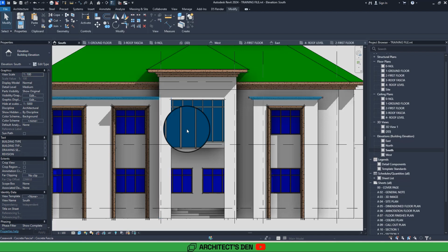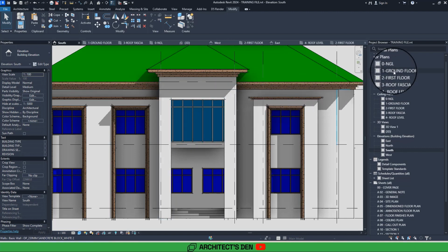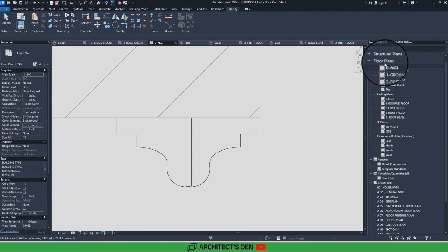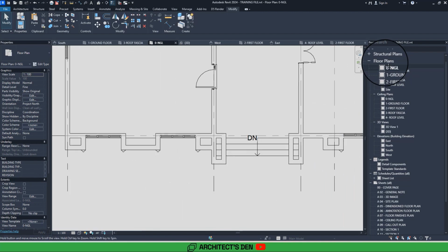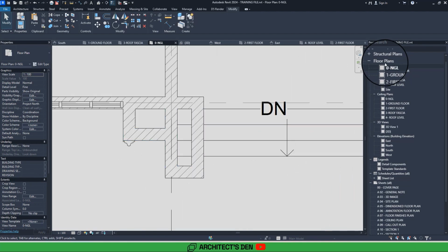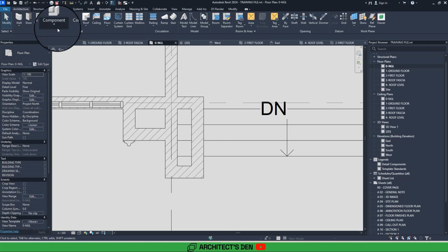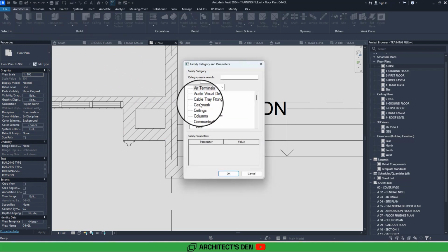We can use sweep to do that. So I'll start with sweep, create something like a base here, a top here, and then we can use plaster finish for all these things, or concrete, sandcrete molding in the finishes. So let's give that a try. I'll go to the floor plan and I want the casing to be somewhere around here, this way. So I would start with architecture, model in place, and call this casework.